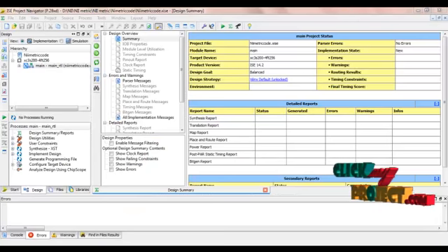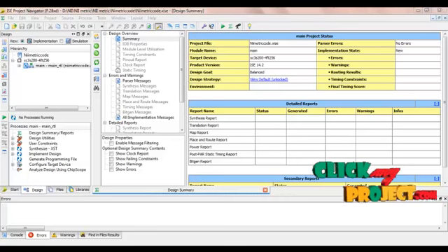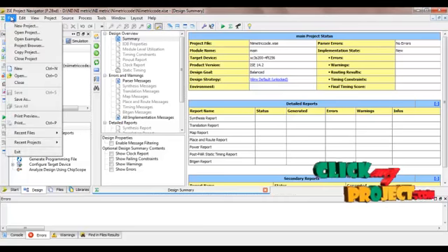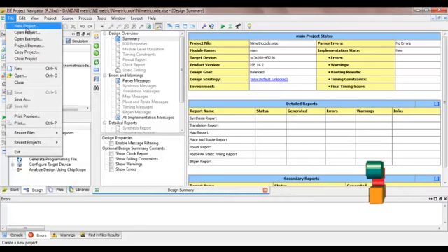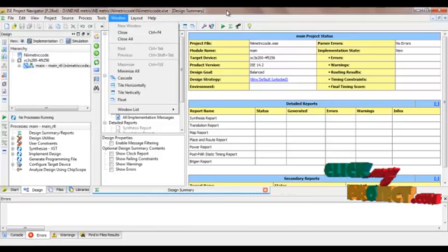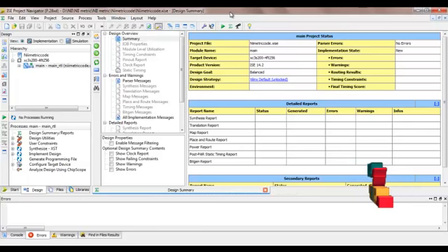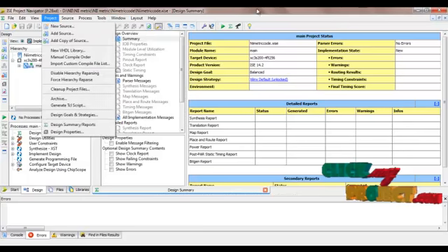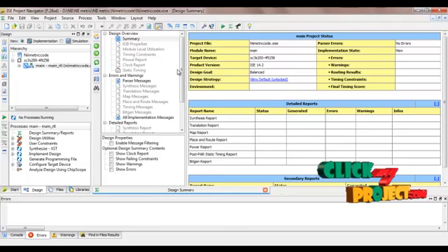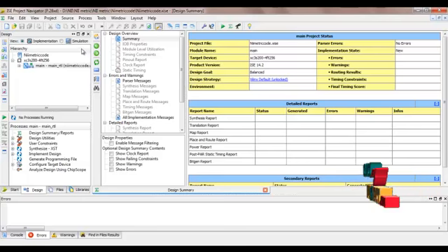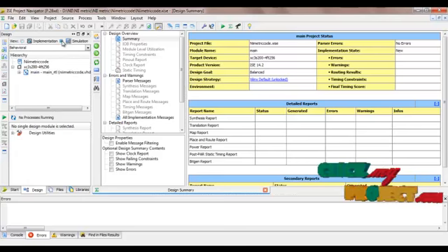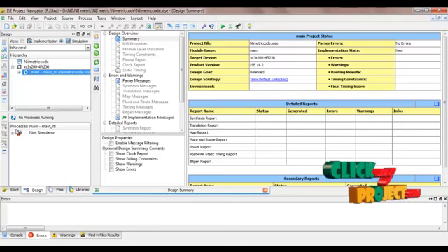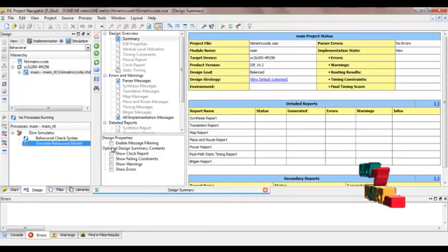Finally, we are going to see the output for our product. We use the software Xilinx version 14.2. To create the new project, click on File and then click the new project. Specify the folder to which we have to save our project. Then click on the project new source to create the program file. Then add it to our project. Here, to simulate the code, we have to click on Simulation, Main, and then Simulate Behavioral Model.